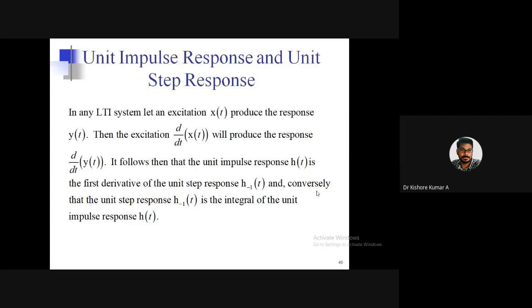So, unit impulse response and unit step response. In any LTI system, let an excitation x of t produce the response y of t. Then if we differentiate, x of t will produce the response d by dt of y of t. So we can conclude that the unit impulse response h of t is always the first derivative of the unit step response.